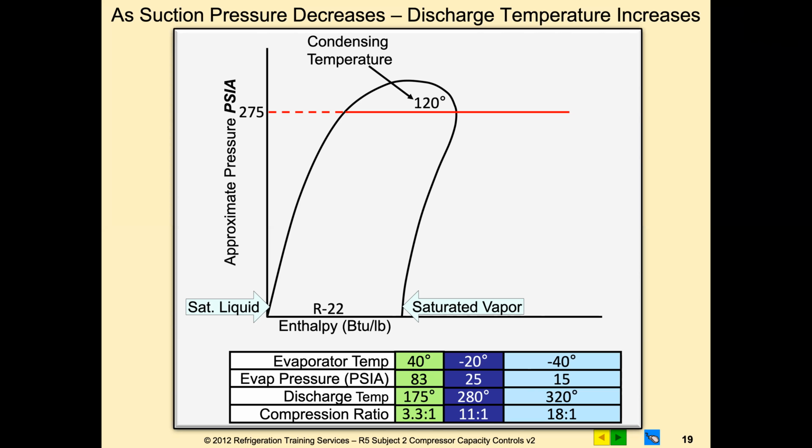The only thing they've got on the suction side was a pressure transducer, just for monitoring, which would also include the low pressure cutout. We sat in on a thing last year where they're wanting to come up with an anti-slugging flooding control, and I know they want to tie it into that Dixell controller since they purchased them. I didn't know if it had hit the market yet, but we should start seeing that pretty soon in the field.